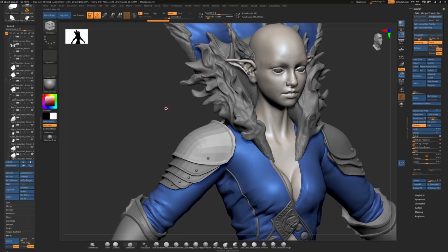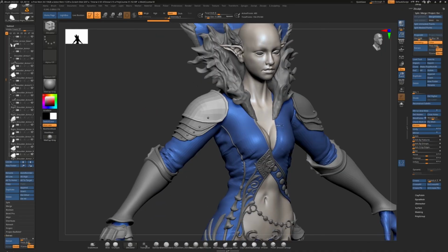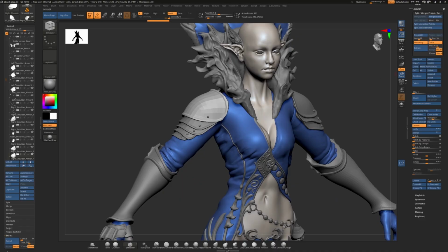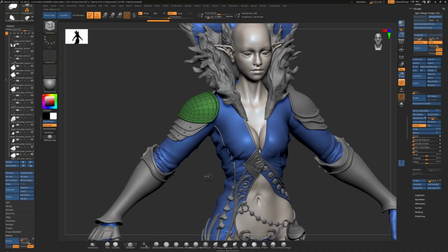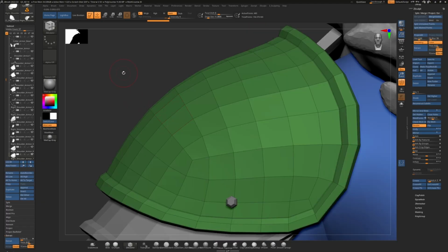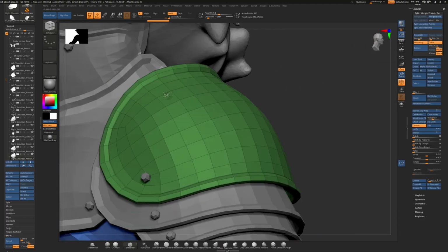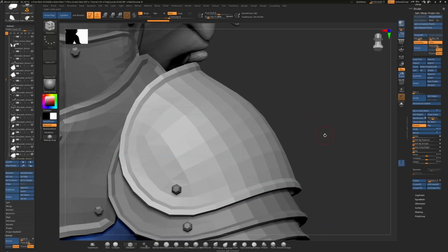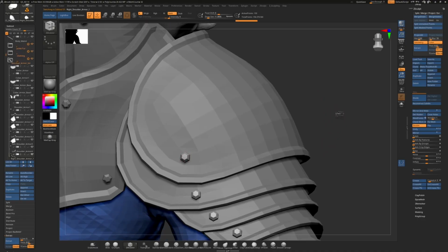All right, so with all that out of the way, let's start looking at all the armor pieces, because one of the main reasons we did a lot of remeshing and projecting was so that we could find a low poly form of each model that we could possibly export with UVs already on it. That's why I typically, aside from also trying to use Noisemaker or apply surface noise, which needs to have UVs on your geometry, do the same thing with adding IMM brushes or curve brushes that have texture detail or have UVs on them.